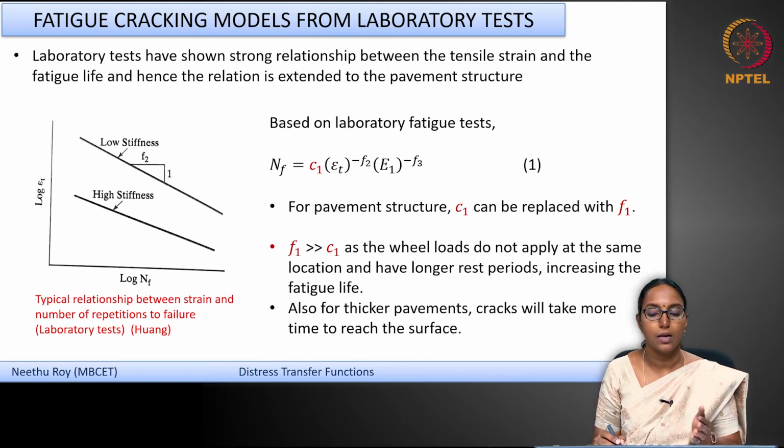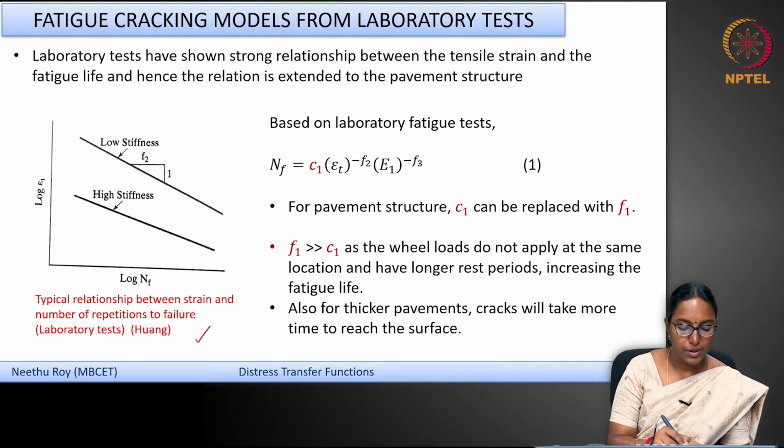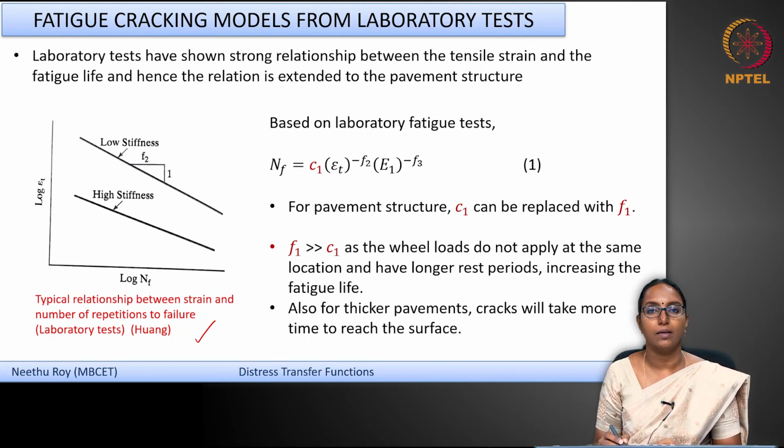Okay, so this relationship actually can be extended to the pavement structure. So, this is what has led to the development of fatigue cracking models or the distress transfer models. Okay, so you can see here there is a picture shown which is a typical relationship between the strain and the number of repetitions to failure on a bituminous mixture in the laboratory.